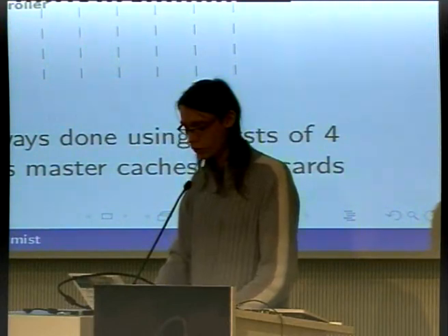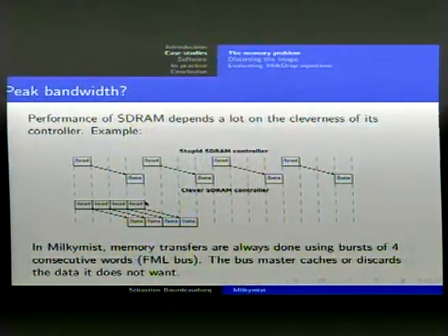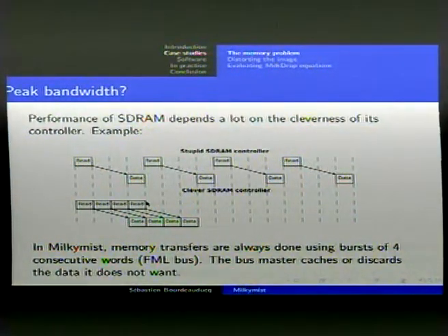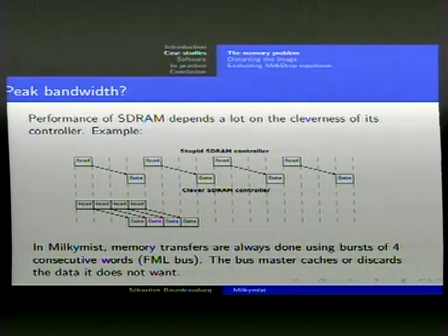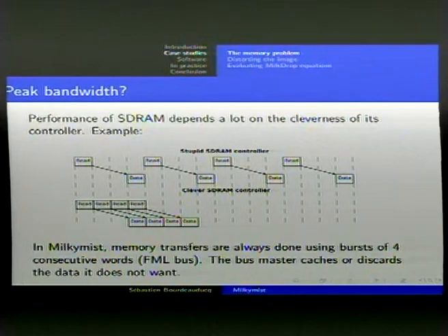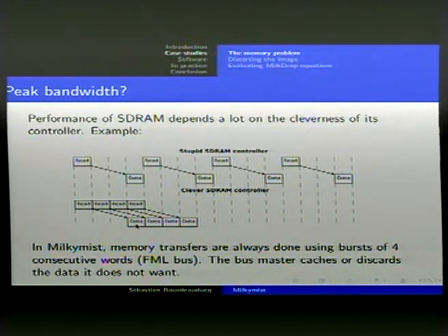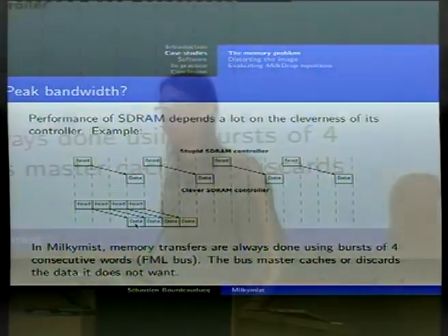If you want to predict the address sequence, it's hard, because typically if you have, for example, a for loop, the CPU must be able to do some kind of speculative execution. If you want to copy 2 buffers, for example, if you load one word and then store it in the next, you have to reorder the instructions in order to be able to continue execution, even if the memory has not given you the data. But you need to continue execution to compute the next address, and that's pretty hard to do in software.